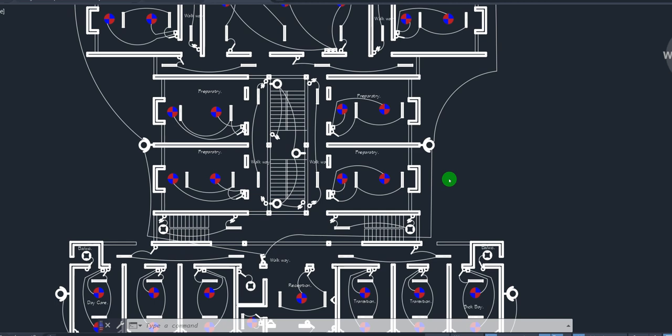All of them will come on at the same time and go off at the same time. It can be more than 50 lighting points controlled by that same system, depending on how you segregate your load and the strength of your switching system, that is, the switch rating of your switch.